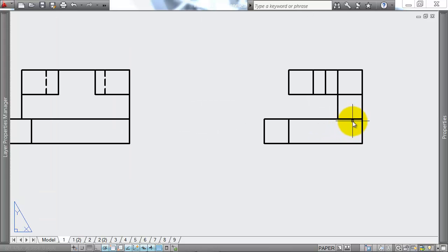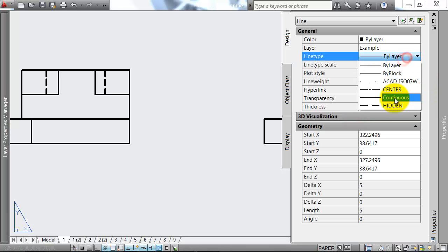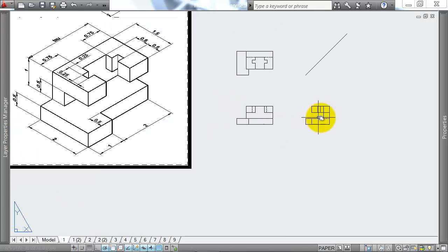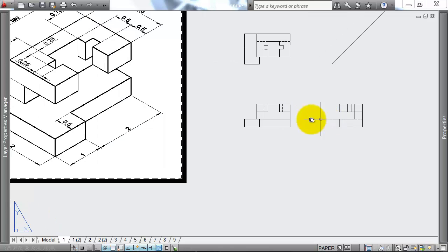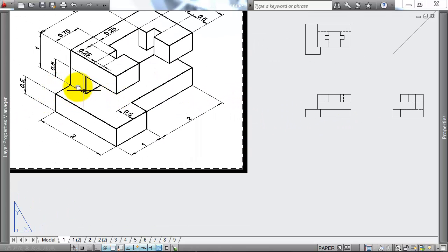Now, as for the end of this line, we would have a line there, but not a solid one. If you look, I'll make this hidden first. And if you look through this shape, so from this view here, looking through the shape, you'd come out the other end, and then you'd see this edge here. So that edge shows up as a hidden line.